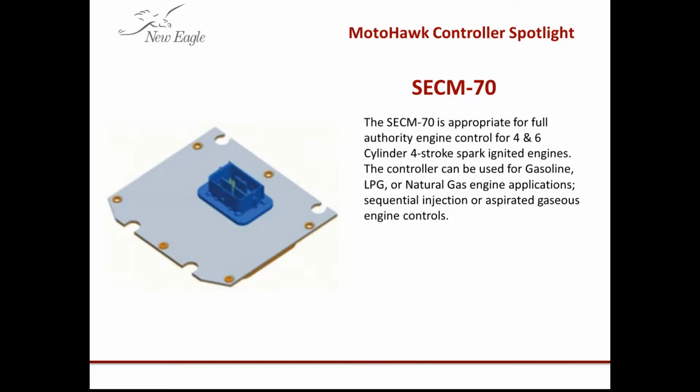Continuing to talk about this newer 70-pin module, it's one of the new ones that Woodward has come out with. Like I said, it's appropriate for full authority engine control for 4 and 6 cylinder, 4-stroke spark ignited engines. It can be used for gasoline and also alternative fuel engine applications. It's got sequential injection or aspirated gaseous engine control capability.